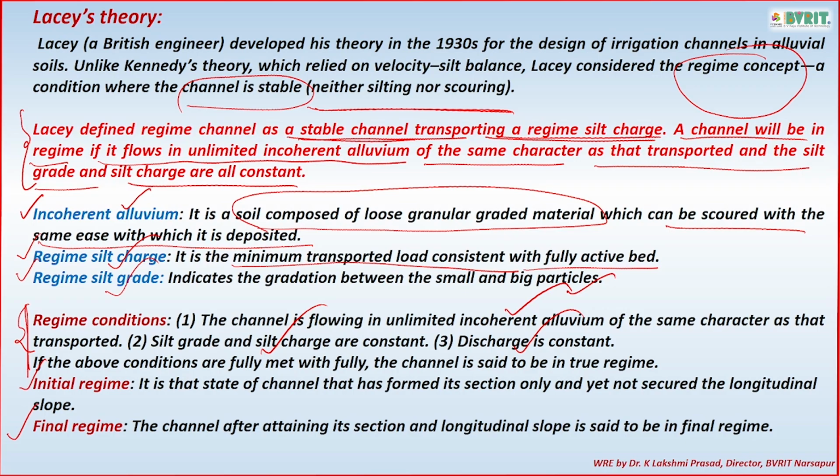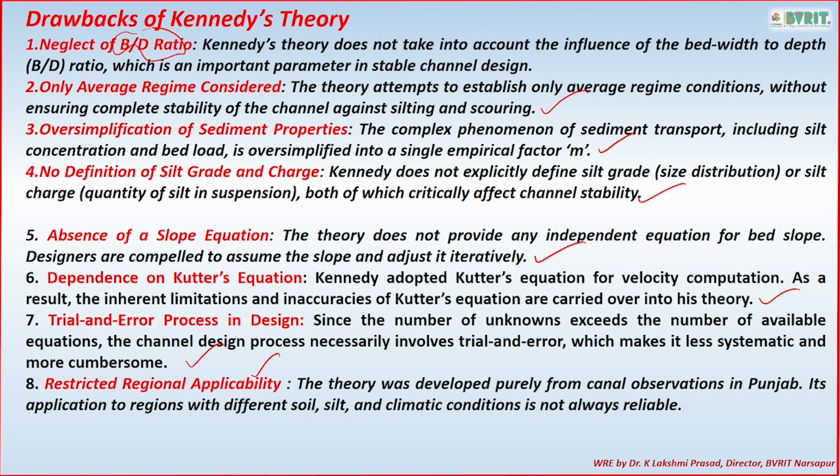What is final regime? Final regime means the shape, that is the section, and section means the sizes, bed width, side slopes, everything. So the channel after attaining its section and longitudinal slope both is said to be in final regime.